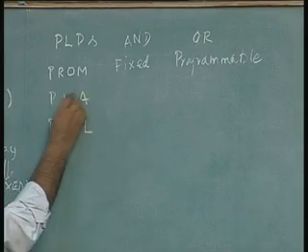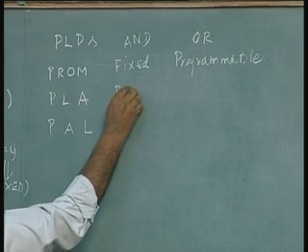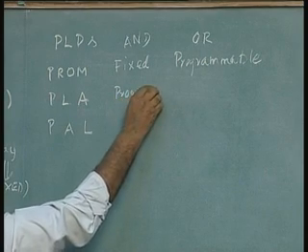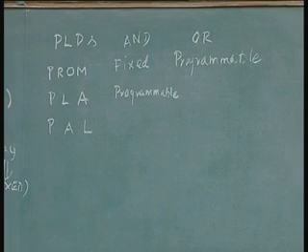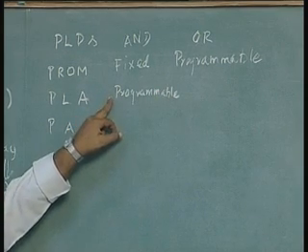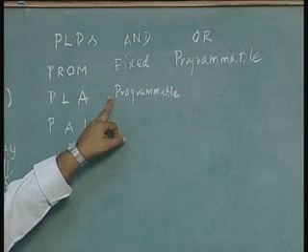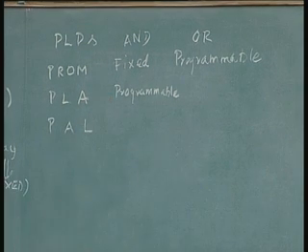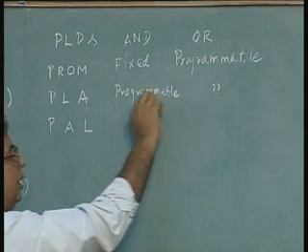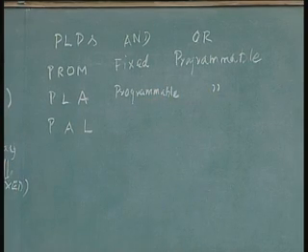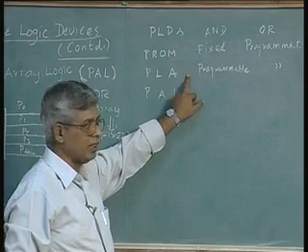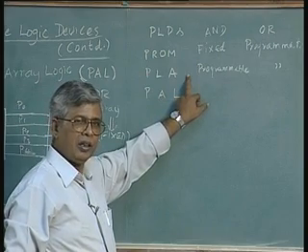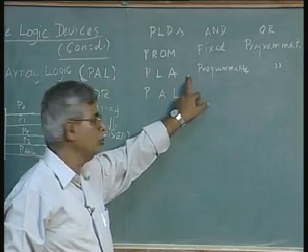In a programmable logic array, the AND array is programmable. You can generate min terms, you can generate product terms by any combination of the inputs by giving the appropriate inputs to the AND gates, and the OR gate is also programmable. You can combine the product terms so generated in any manner you like to form the output functions. The design concept here was to minimize the functions, but keeping in mind to have as many common terms as possible.